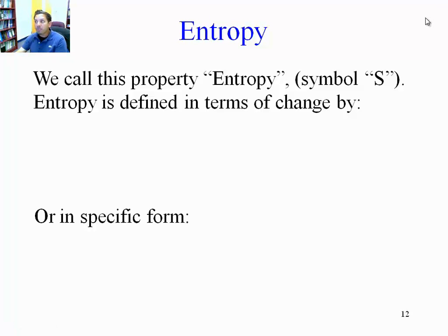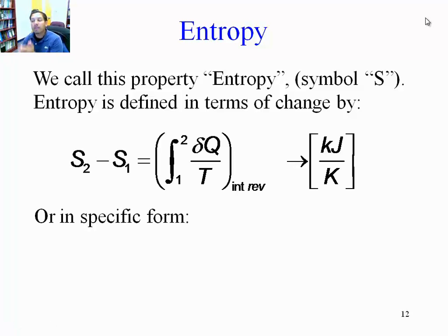And S, entropy, is basically a strength of the irreversibility of a process. We said that this integral is equal to the change in entropy only for internally reversible processes, but we're not confining that to externally reversible processes.